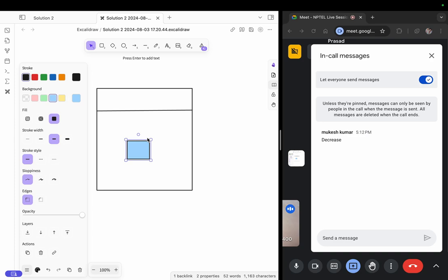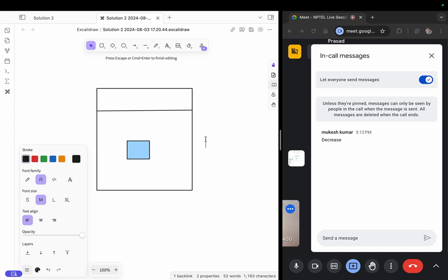And what is that pressure? That pressure will be proportional to the total fluid on top of that element. So the weight of this entire thing is being felt by this element. That will be my hydrostatic pressure. So if I consider this bottom point, the total pressure will be rho g h.